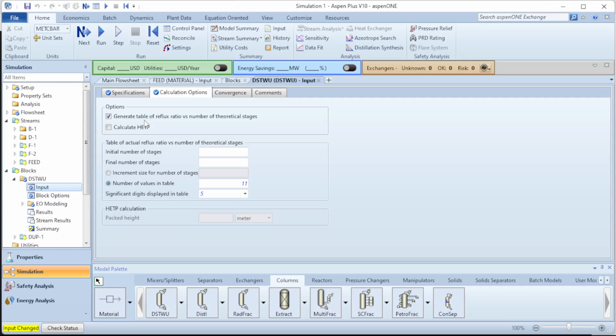And once that one is increasing, it means that the cost that we are supposed to incur during the operation of the column needs to go up. So as reflux ratio increases, you will see that the operating cost will increase. But the initial cost, which is the capital cost that we will need to install the thing, will be low. So you will get it very well.